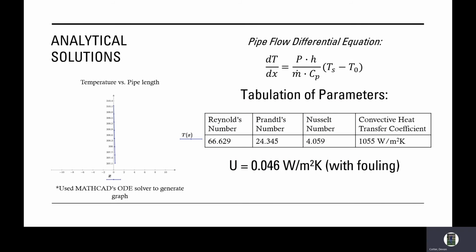The temperature profile was constructed from the differential equation outlined on the slide. This pipe flow equation serves as an energy balance for an arbitrary flux of heat through a blood vessel. From this temperature profile along the length of the pipe, assuming cold conditions experienced by a human, you can see the temperature drop along the length of a foot-long blood vessel is rather minute, but is likely and can explain the temperature fluctuations of the body. Ultimately, the steep slope of the plot is met by the extensive insulation due to fat, muscle, and skin.